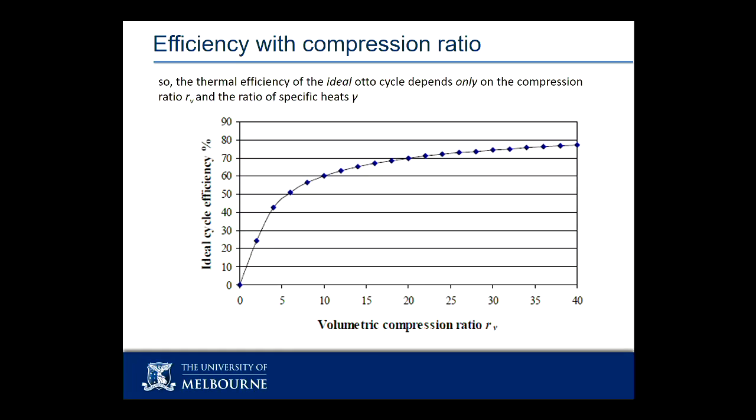And so when you're putting fuel into your engine and it's got a 91 or a 95 or a 98, these are referring to how resistant these fuels are to auto-igniting, to going bang. The higher the number, the more resistant they are, which means the harder I can squeeze them before they catch fire. So if I can squeeze them harder, I can get more efficiency out of my engine. So if I design my engine to squeeze harder, I better make sure that I match it with the right fuel. If I put a 91 fuel into a 98 capable engine, it's still going to try to squeeze all that way, but the fuel I've put in is going to go bang beforehand.